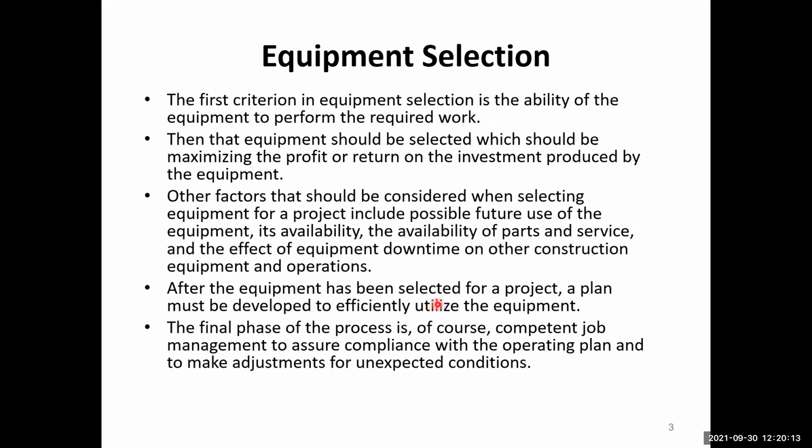So after the equipment has been selected for a project, a plan must be developed to efficiently utilize the equipment. We have our master plan for the project based on the project activities. That master plan, which is based on the critical path method, we can use to also schedule the equipment. That means we can resource load that plan with the help of the equipment. And then using our software, for example, Microsoft Project or Primavera P6, we can create the resource schedule that will be based on each type of schedule. And then, of course, that schedule includes the